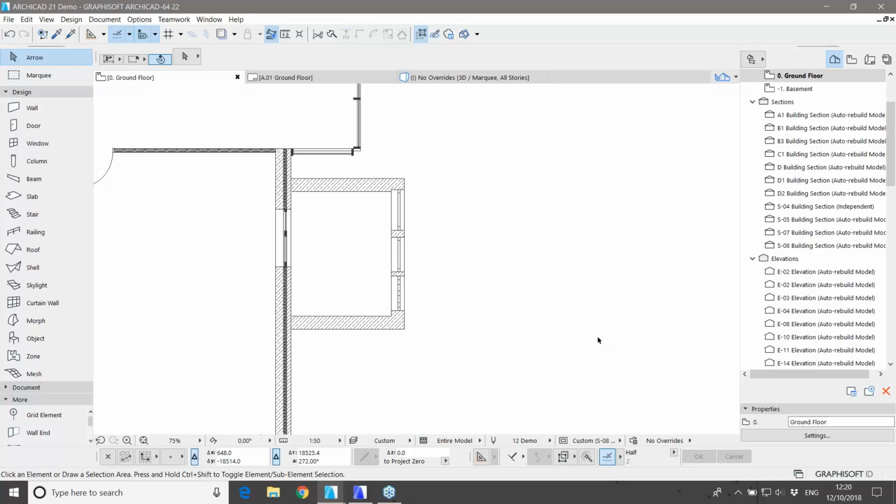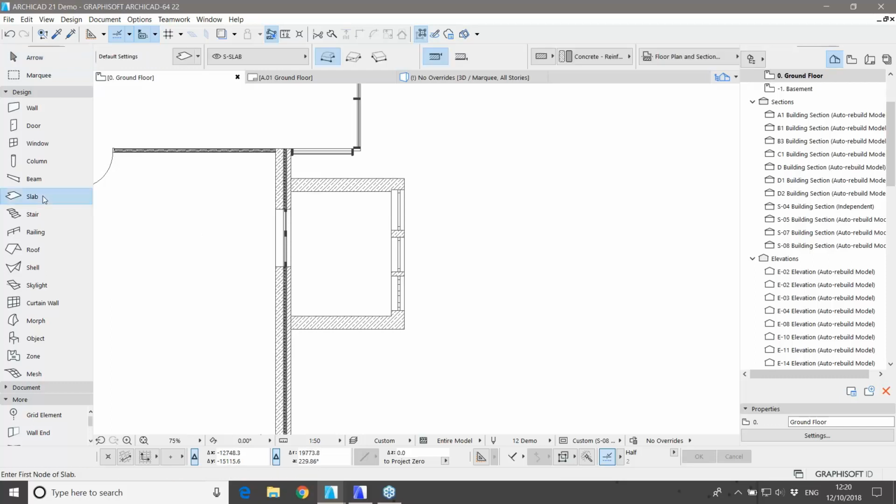Let's continue with the slabs, with the floors. So this is probably my favorite tool in ArchiCAD. Again, we're going with a single skin slab because I don't know what the build up for my floors is either. We're still at the conceptual stage. With the slab tool, this is an easy shape. It's a square or rectangular building. So I could just go corner by corner and place my slab. But you will notice now my arrow changes into a magic wand. Like I said, this is my favorite tool.